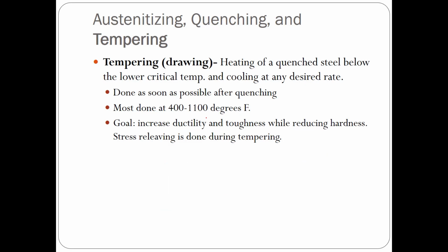Tempering. So when do we temper? Time-wise, you try to do it as soon as possible after quenching. When is it necessary to temper? If you form martensite, you should be tempering it. That's just the bottom line.